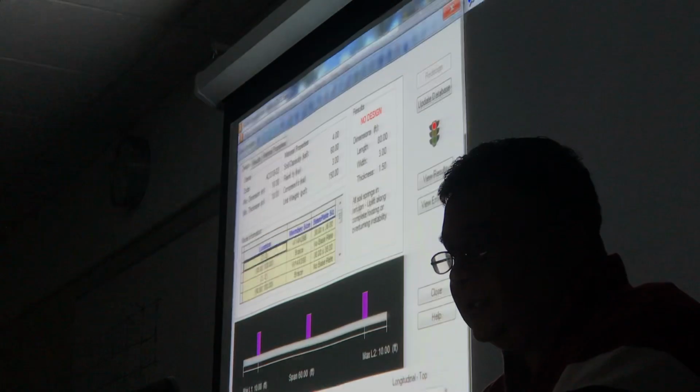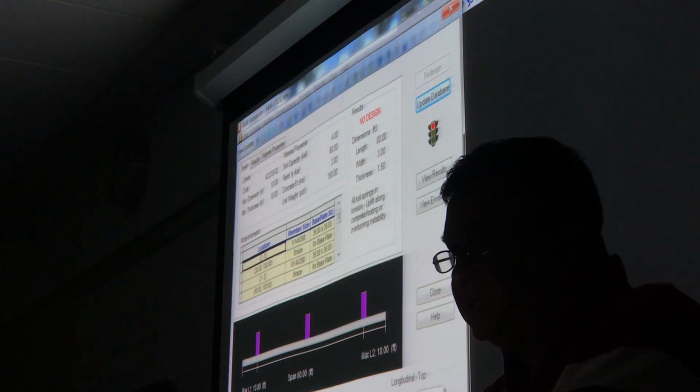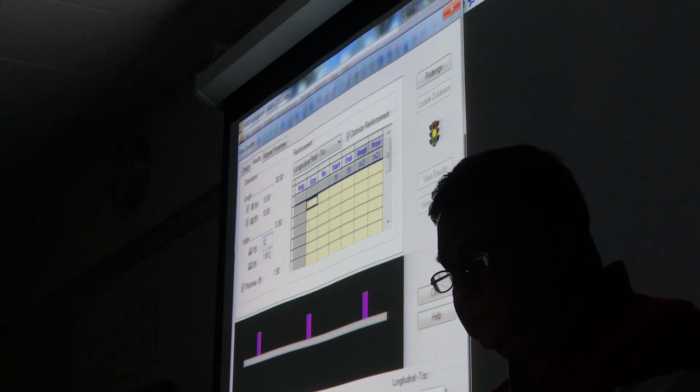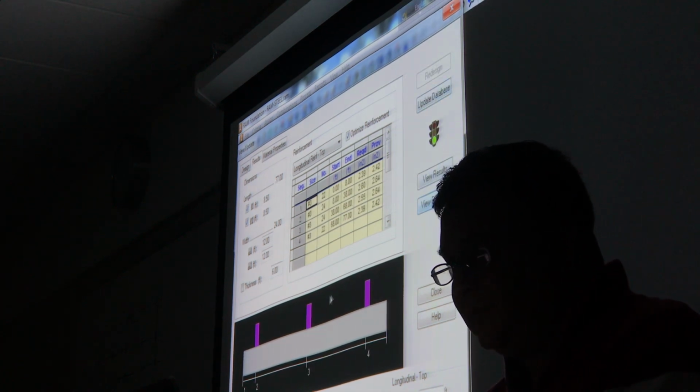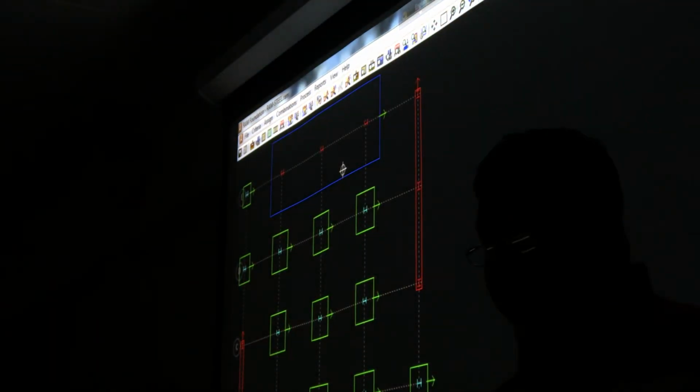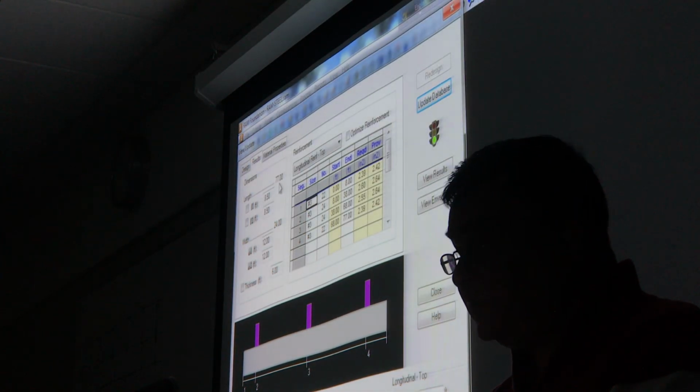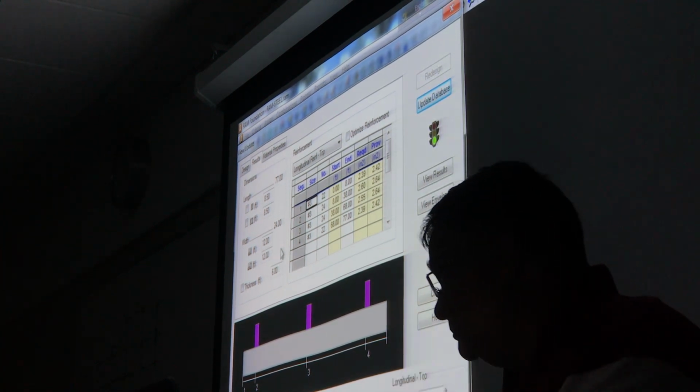Okay. What about this one? These are not done yet, so we can click on that. And what does it say? All springs are in tension. So what we need is pump up the size. Okay, so it works. What is the size of that foundation? Now you'll see that the size of the foundation is 77 feet long, 24 feet wide, 6 feet thick. But is that normal? Yeah.